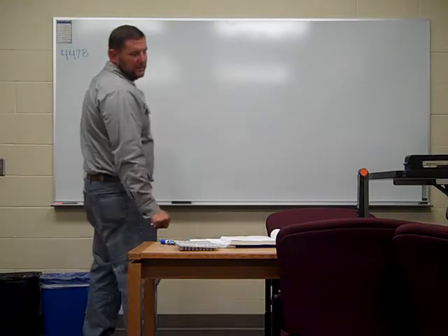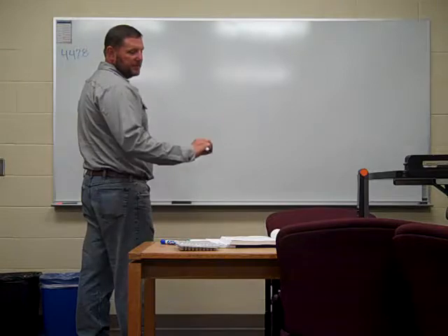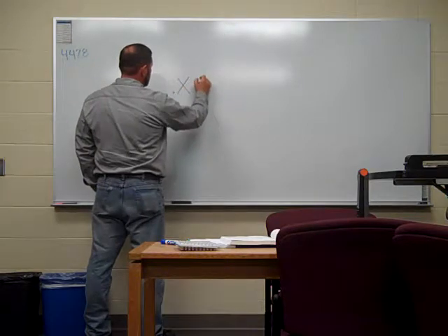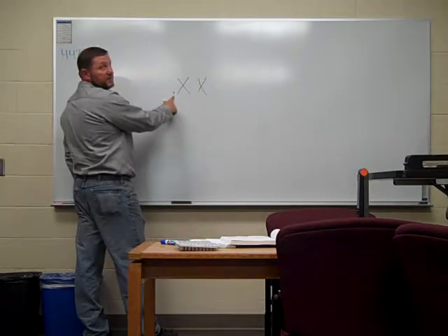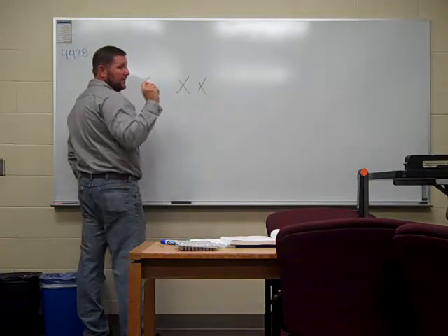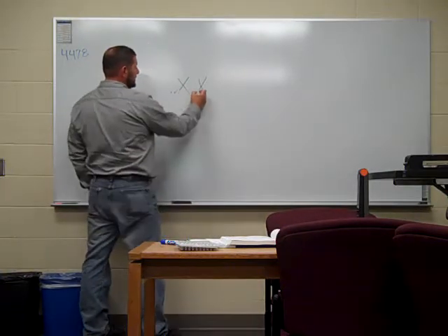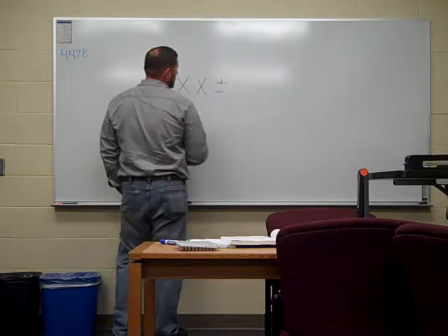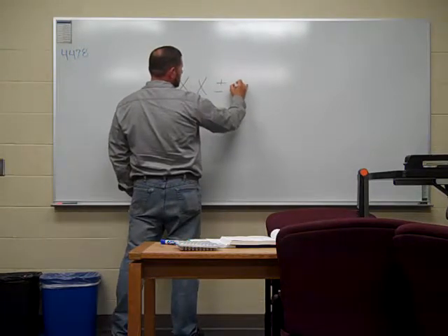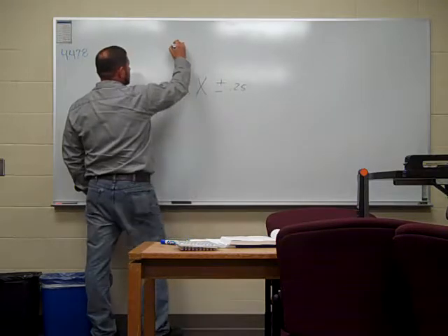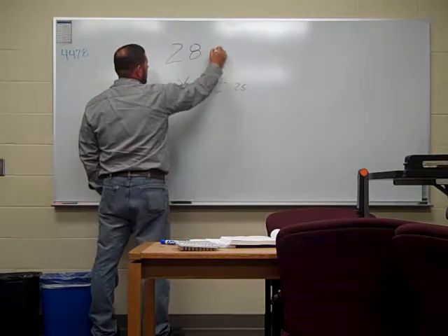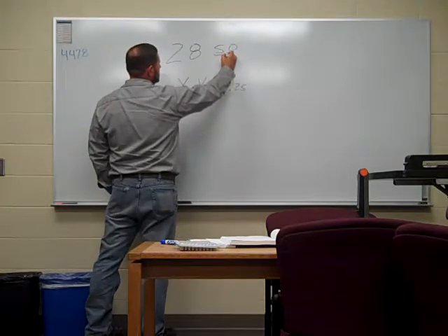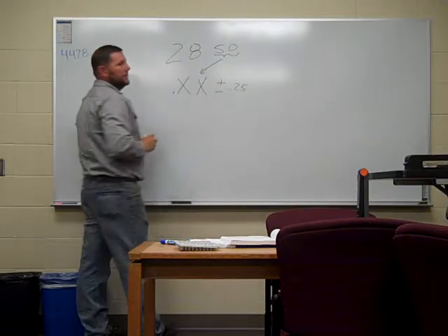As you see in figure 9.13, you see general tolerances listed there. This is the big one. You notice it says X X with the decimal point in front of it. That means any dimension on that print that has 2 decimal places is going to apply to that tolerance. I'm going to use 0.25. So if my dimension is 28.50, I have 2 decimal places. That applies to that tolerance.